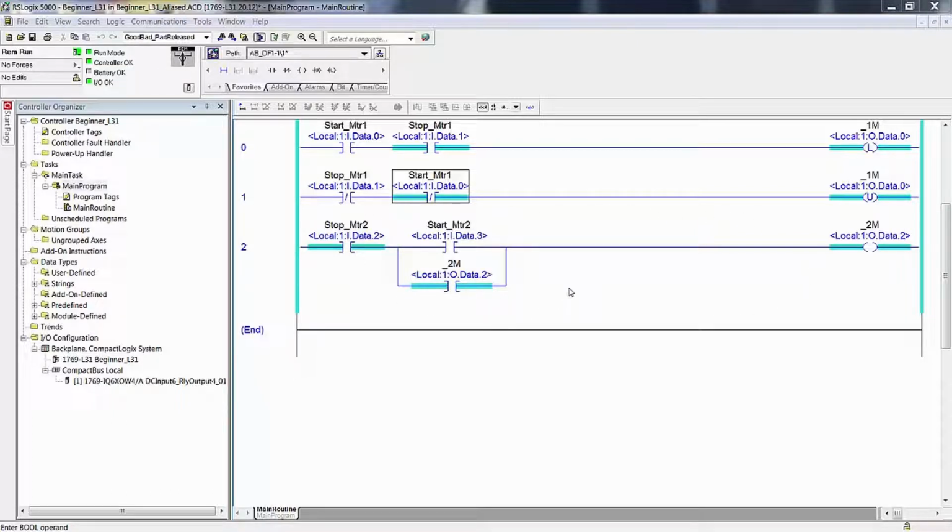Plus, if I'm actually starting or energizing field devices that can cause motion, like solenoid valves, motors, etc., I want those outputs to drop out if they go into the program mode. I don't want them to turn it back to the run mode and then all of a sudden have some unexpected motion and something gets damaged, especially if it damages the operator.